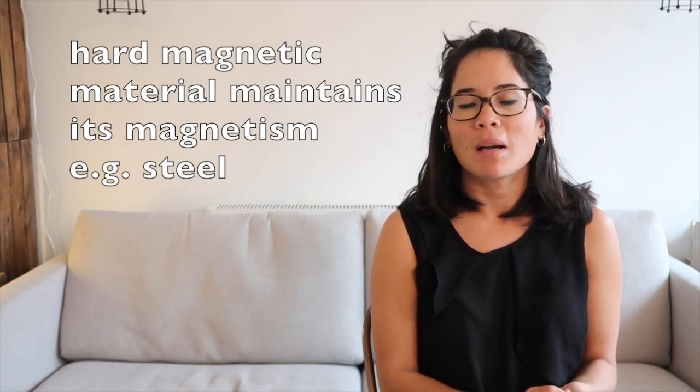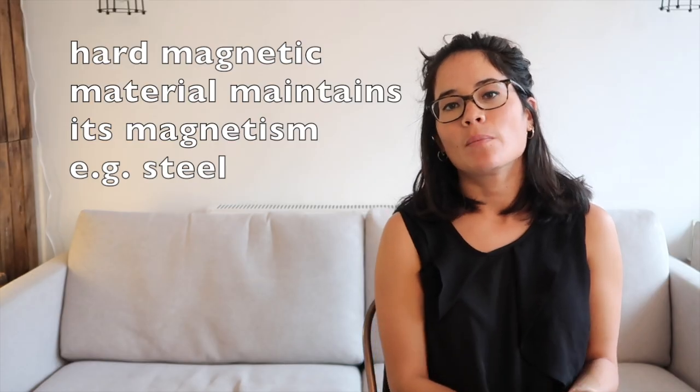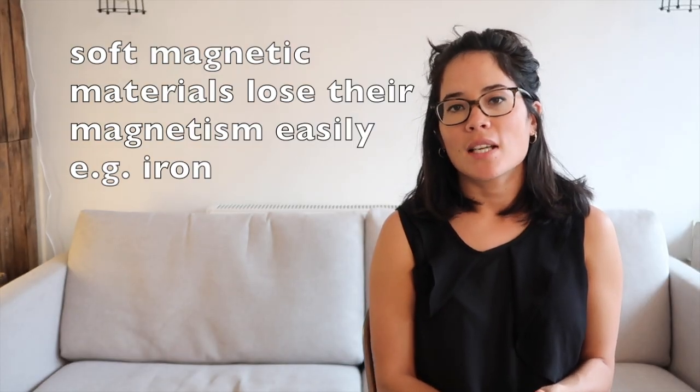Looking at the difference between a soft magnetic material and a hard magnetic material now, the real difference is that a hard magnetic material maintains its magnetism. So steel, for example, is a hard magnetic material. It does not lose its magnetism easily, whereas iron loses it very easily. And to put this into context, if we use a scrap metal yard as our example here, scrap metal yards are full of big old lumps of iron which need moving around. Now you actually use a magnet to move them around, and what you do is you turn on a massive iron electromagnet and it becomes magnetized.